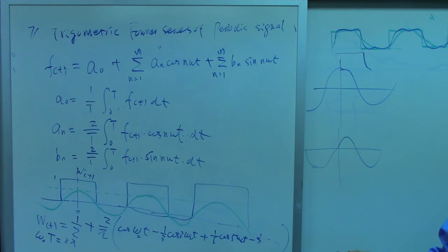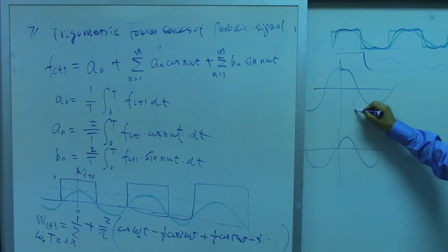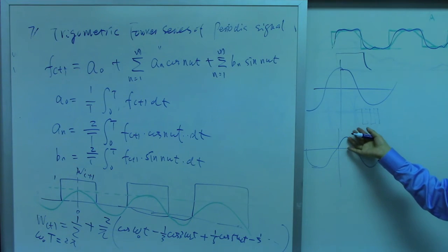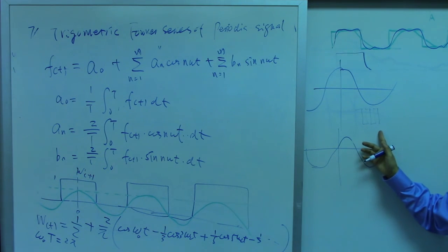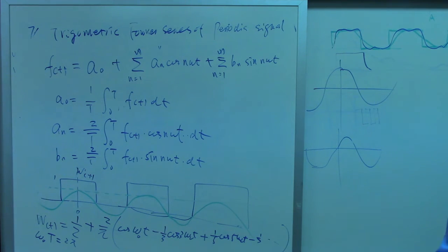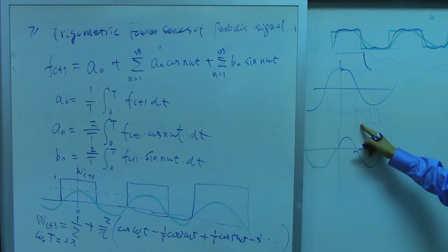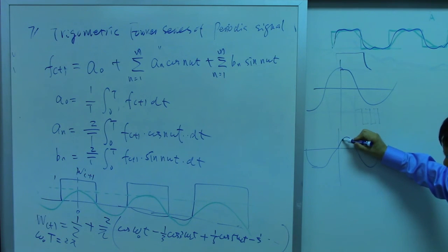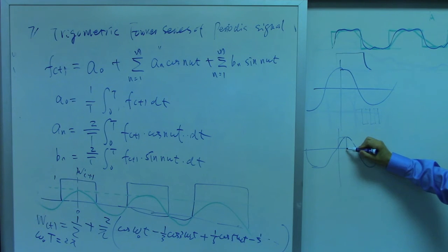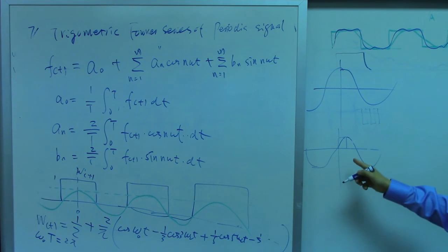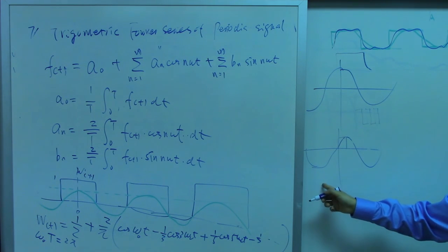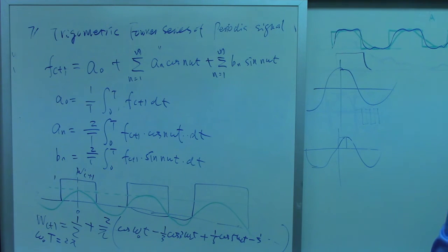For example, now most of the communication systems are digital. Digital means you transmit 1, 0, 1, 0, 1, 0. If your system is ultra wide bandwidth, you transmit 1, 0, 1, 0 perfectly like this, then I can make these pulses very narrow because it's up, down very fast and perfect. So I can still distinguish this 1, 0, 1, 0, 1, 0. That means I can transmit the data very fast, so the data rate is higher. But if your bandwidth is limited, when you transmit 1, it goes up slowly. When you transmit 0, it goes down slowly. The pulse is down, but you still need some time to fall. Before it finishes falling, the next one comes, and now you will mess up. So if your system is not ideal, then you cannot transmit 1, 0, 1, 0 very fast. Your transmit rate is limited.